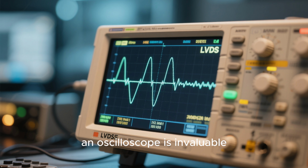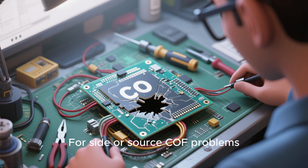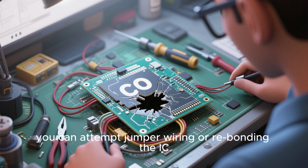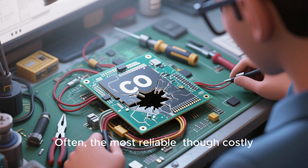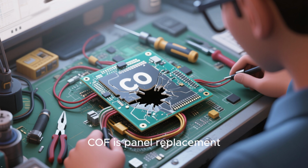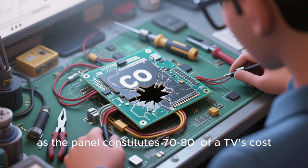COF, chip on film issues, four-side or source COF problems. You can attempt jumper wiring or rebonding the IC, but these are delicate procedures. Often, the most reliable, though costly solution for a severely damaged COF is panel replacement, as a panel constitutes 70 to 80% of a TV's cost.